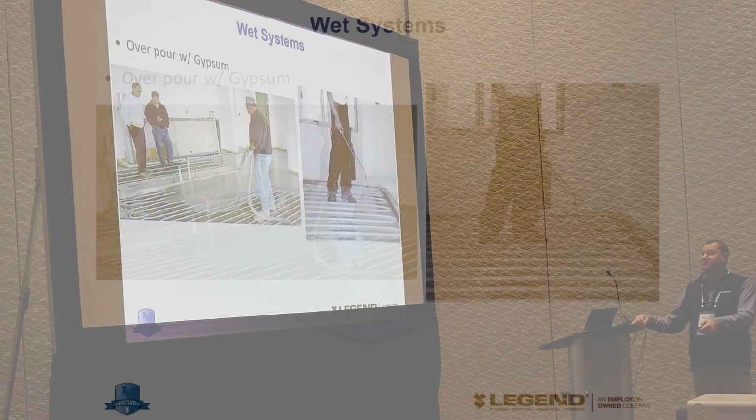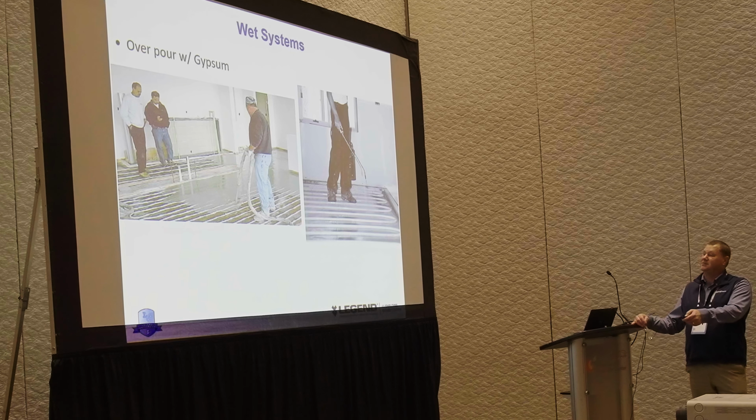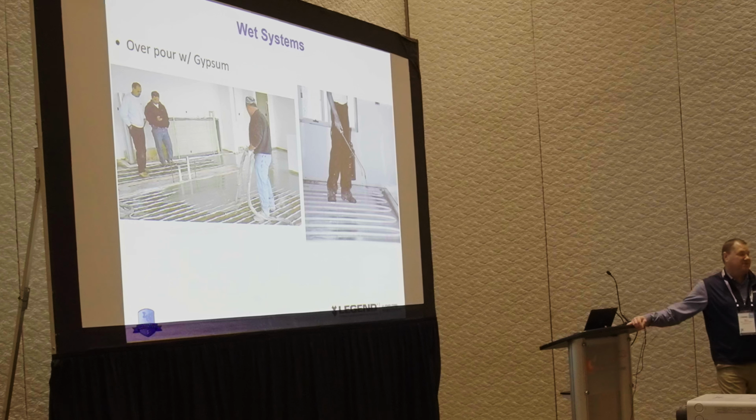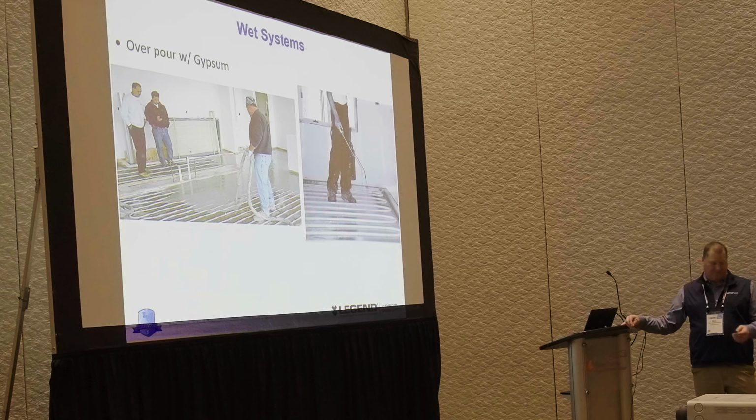And if you're prepping a gypsum project and you don't dam off those tubes right there, or any place there's a penetration in the floor, stuff's like a melted milkshake, it's going to go right down through there. So you got to make sure you really prep your floor well, and then make sure that they install it properly when it goes in.